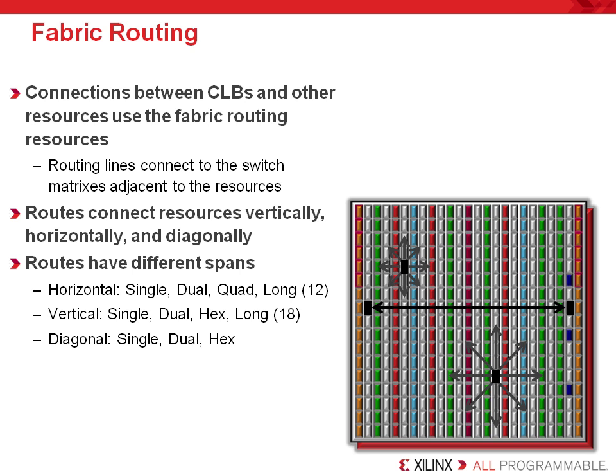The types of routing resources vary by length and refer to the number of columns or rows of CLBs they span. In Virtex 6 and the 7 series, all routing, besides the carry logic resources, is routed through the switch matrices. While understanding the interconnect structure is not needed, this diagram is meant to describe the population or the ability of the routing resources to interconnect between slices and CLBs.